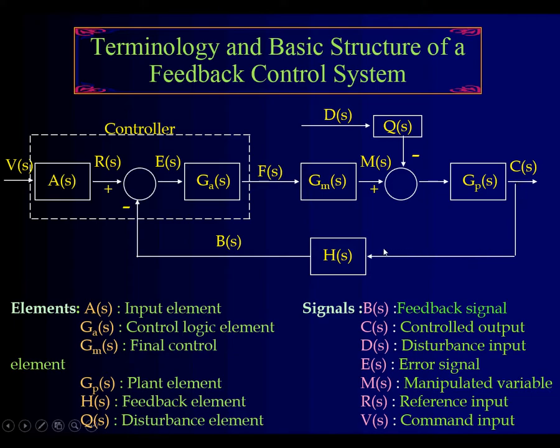You measure something, and that is some sort of analytical measure of a physical variable, let's say speed. This is transformed into a voltage. This is the reference, R for reference, and the difference between the reference and the feedback signal, all these things have to be in the electrical part.